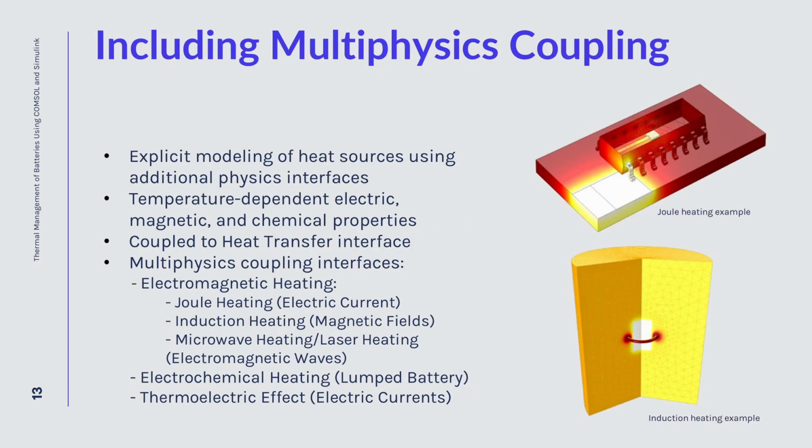Also, to couple to physics other than heat transfer, you could include, let's say, a Joule heating example here. So if you have some electromagnetic source that works as a heat source, then this can be coupled into your model. The properties can be temperature dependent, and you can use these variables during your simulation.